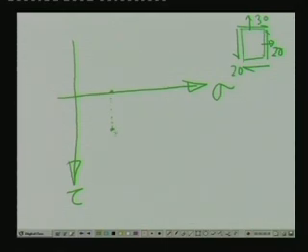Now, this particular shear stress is positive because the shear stress on this plane and the complementary shear are making a rotation which is anti-clockwise in nature, which we have called as positive. So, this is 20 and this is 20. Let us represent this plane which is 90 degree with respect to this x plane. Eventually, in Mohr circle it will be 180 degree.